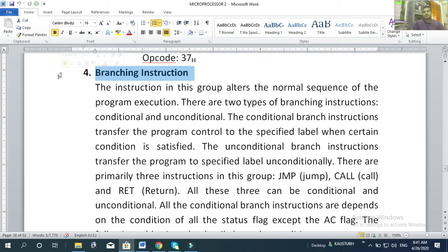At the very beginning, the address of the first instruction is given to the microprocessor, actually to the program counter. The program counter will assist the microprocessor and give the address to the address bus. Then instruction 1 will be fetched, and while the microprocessor is executing instruction 1, the program counter is automatically incremented by 1. That means it holds the address of the next instruction to be executed. That's how the program counter gives the sequencing of execution.